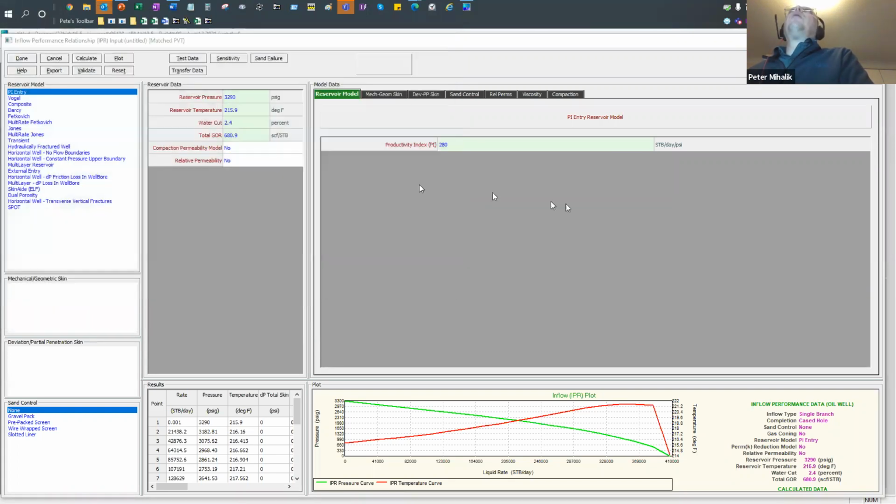And you'd use that one primarily to calculate IPR models for tight wells if you've got multiple fractures. But MBAL itself also has modeling routines for tight oil and tight gas reservoirs. So you typically get the IPR model maybe from that and then tie that to a wellbore description via GAP.